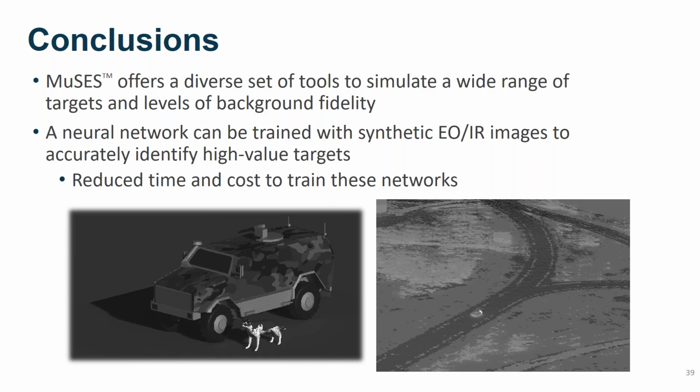Yeah, for sure. There are best practices. So we've developed some guidance for mesh resolution and how to make sure that your surfaces are properly connected to capture the right conduction paths. Either we can send you documentation, or we've got some mesh guidance documentation on our customer support site. So I'd recommend logging into the customer support site to check out some of that, or send us a message through our customer support ticketing system, and we can help you with that.